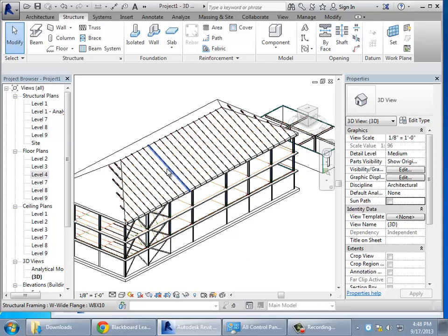So that's the only variation you need to know about for the roof in terms of sloping. Go ahead and use the reference plane to hang on, and then when you put the beam system in, it'll have the reference plane. Perfect test. Okay, we are just about out of time in terms of what's going on there.